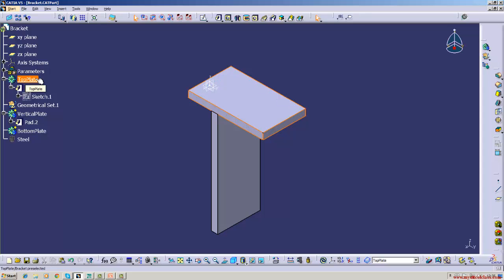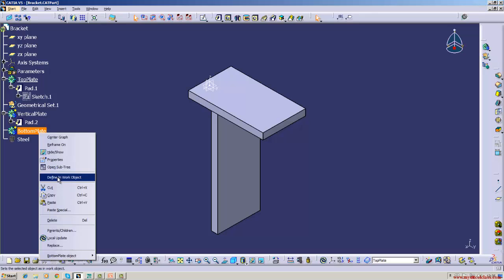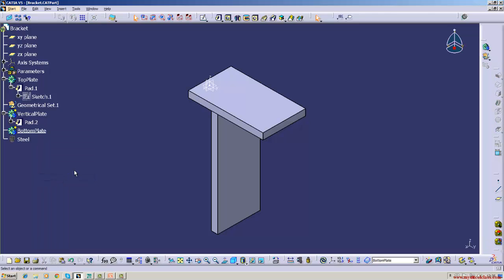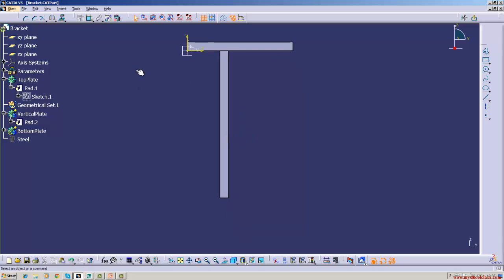So what we have to have? We have to define the work plane for the bottom plate we are drawing. Define the work plane. So now when you draw the sketch, it comes under that work plane. So select YZ. Select like this, and then you can just highlight. Then this tracing is selected. Click it because this should not be aligned.